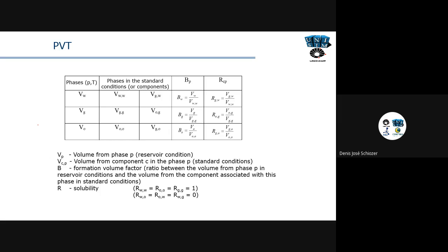when they write the reservoir simulation equations, they write component equations considering the volume, conservation of volume. But we cannot solve it for pressure, for phases, because the phase is changing with pressure and temperature, and the volumes also change with difference in pressure and temperature. So the right thing to do would be to conserve mass and not volume.